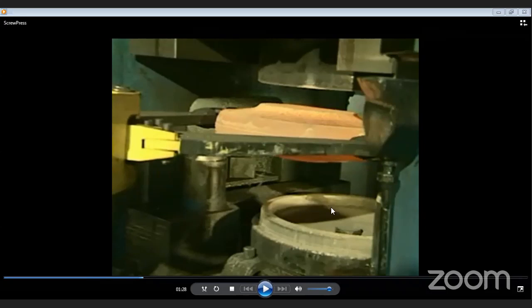There can be an error in alignment of the upper die and lower die. The alignment should be proper for proper manufacturing or forging process. Otherwise, your edges will not get matched properly. So these two guide pillars get inserted in the guide bushes, ensuring the alignment of this die.